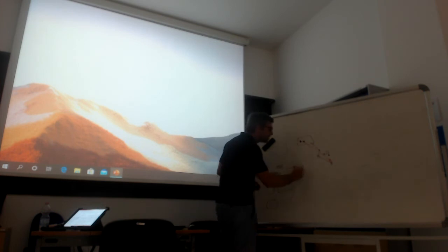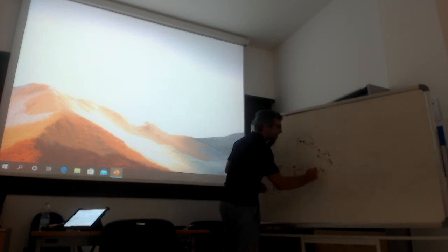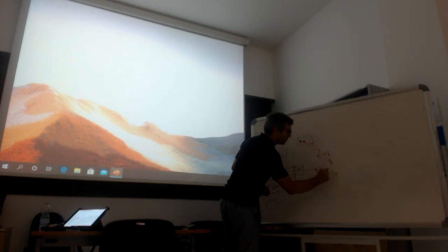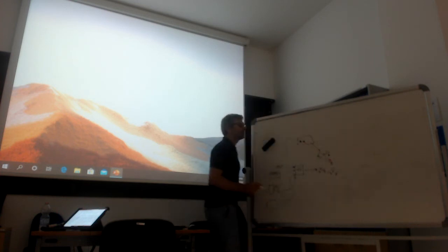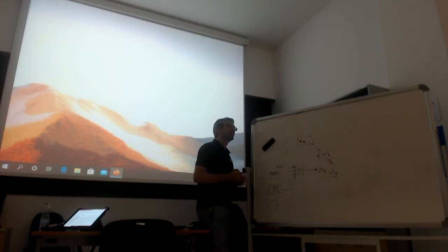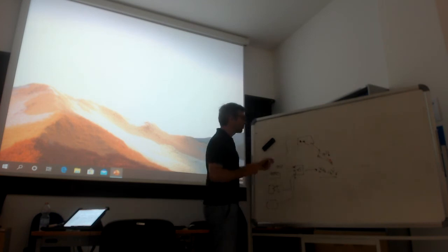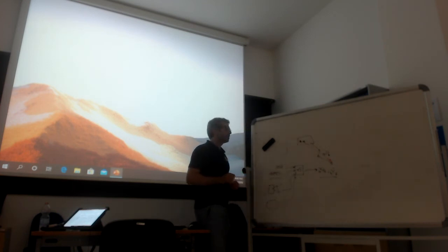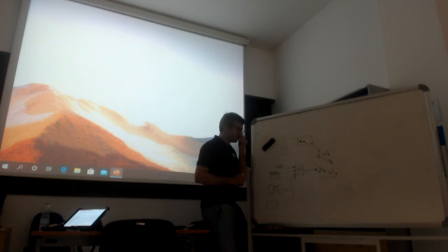And from all this stuff, you get the position of the base in the world frame and the velocity of the base in the world frame. This is your state estimation. But this can be prone to drift. I mean, there is a whole bunch of research in the community only to develop a low drift state estimation.